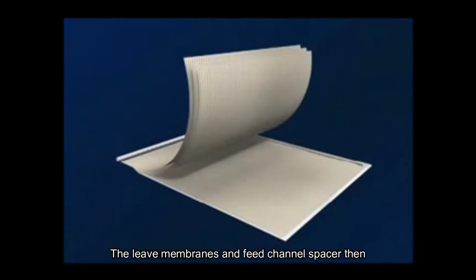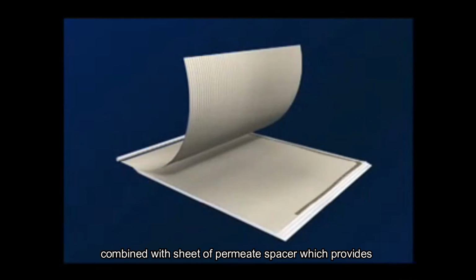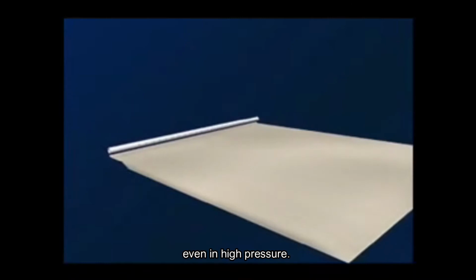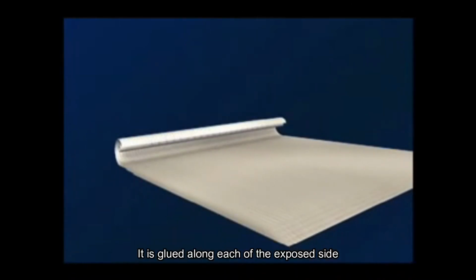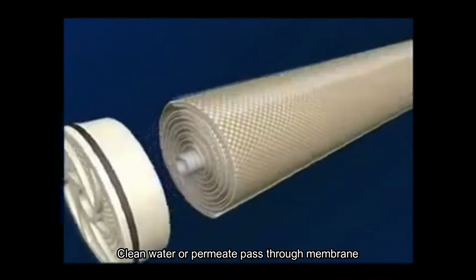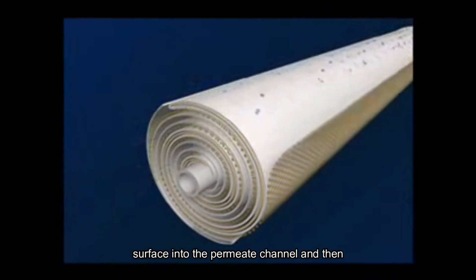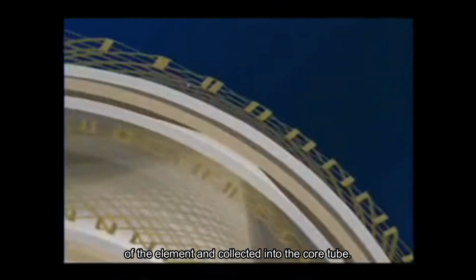The leaf membrane and feed channel spacer then combine with a sheet of permeate spacer, which provides open flow channels for the permeate even at high pressure. It is glued along the exposed sides and then rolled around a core tube. Clean water, or permeate, passes through the membrane surface into the permeate channel and then flows in a spiral direction to the center of the element and is collected in the core tube.